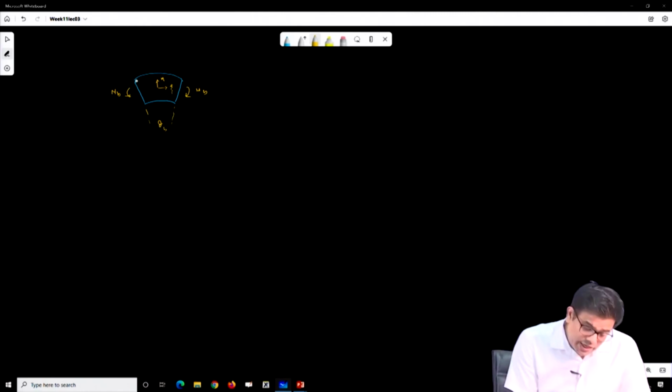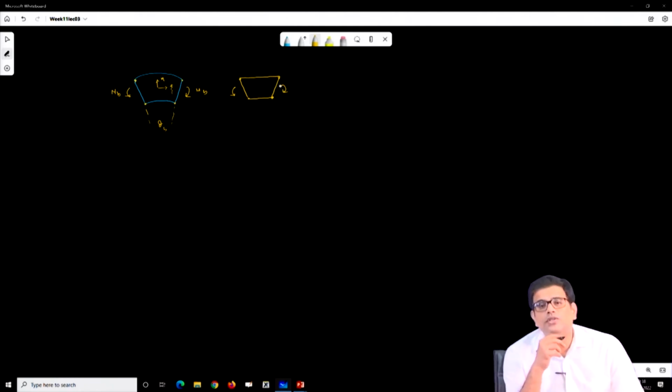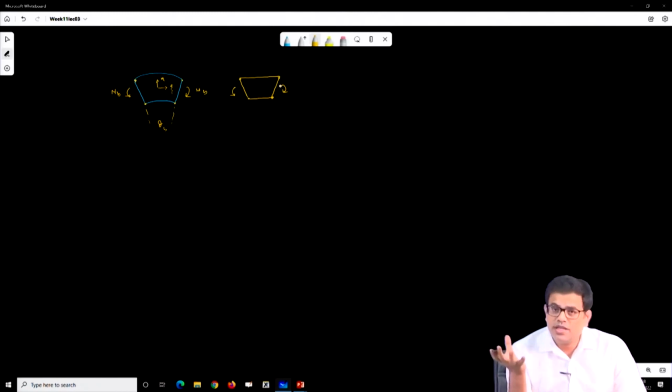Now in this bending problem, what we have observed is that lower order elements, specifically the 4-noded quadrilateral, will behave like this. So this is the 4-node element after applying the moment. The reason it behaves like this is because it is generating spurious shear strain, which we have observed.